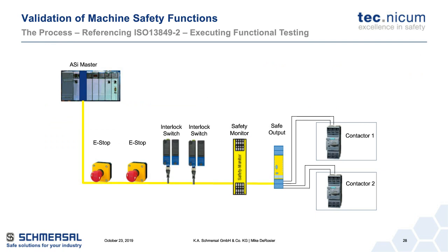What's coming down the line as a result when we look at this? So, safety over networks. I had mentioned safety over Ethernet or Profinet or Profibus. Well, we've got safety on DeviceNet too. So this is a safety network. How do we throw faults into there? This might be doing more by design and less functional testing because of what information we were able to get from the manufacturers, because of the testing that was done at the factory in those particular fault examples and what's being picked up. Doesn't mean we don't validate the software at all.